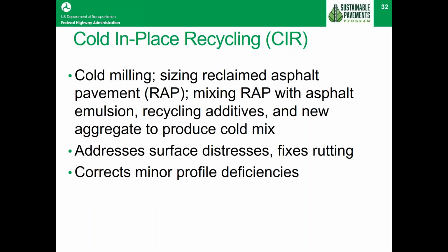Now we also have the other element, which is called cold in place recycling. Now this one, typically, as you can see on the slide there, it talks a little bit about doing this stuff with cold milling. You don't use a lot of heat in this activity that's going on with it. It's not as durable as the hot in place recycling, but then again, it has a lot more application when you're out in remote areas.